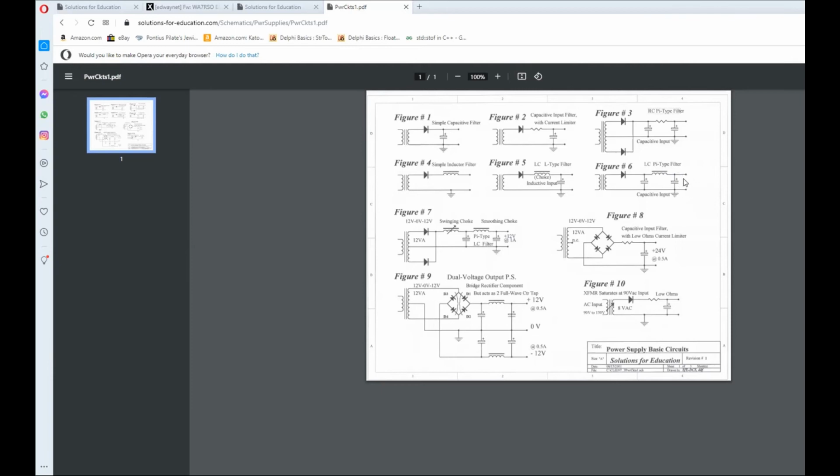Finally, a chief, a fire control chief, who should have known better, pulled the power supply out and put it on a rubber mat. Now remember, ships are made of steel all over the place, but this was a rubber mat. He put it on the rubber mat, but he did not put a grounding strap between it and the frame. That's mistake number one. Mistake number two is he leaned over and his leg made contact with this unit that was sitting on the rubber mat, and he reached over and grabbed hold of a chrome-plated handle to steady himself while he turned on the power. He became the grounding strap, and he paid for it with his life.